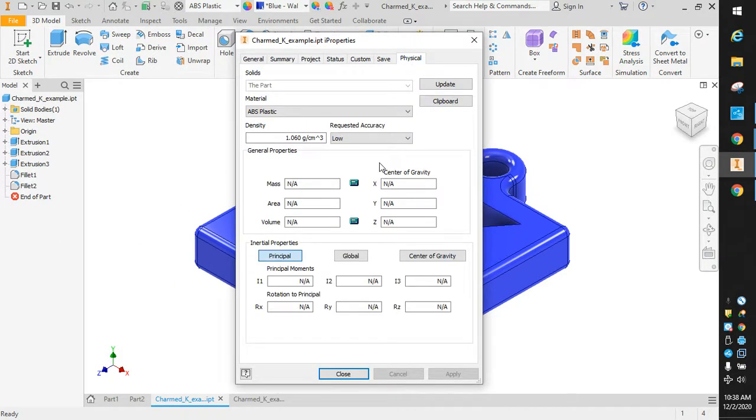That'll give me the physical material properties of this, and I have to hit the update button because now what you see is just the density. Well, let's update that, and then what we want to look at is what's our mass. We've got 0.01 pound mass. We've got the area. We want to know the volume. Make sure that's the key thing we want to look at, what's the volume of this thing. So you want to record these in your engineering notebook because you'll need to put these on your final working drawing for this. So go ahead and put those in your notebook.